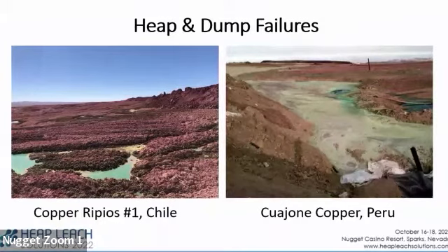We've actually done sample freezing in the Yukon for other reasons. It's a really big deal. So you're just not going to do it. And if you sample this material and then reconstruct it in the laboratory, you're not reproducing the fabric in the field. It's not really the same sample. This is a chemically created artificial soil that hasn't had any time to reach physical equilibrium. It's not like natural soil.